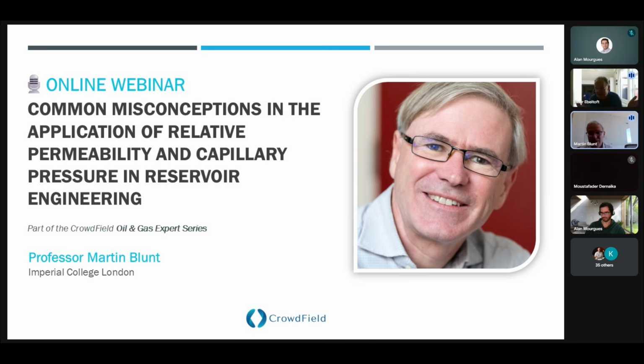Okay, what I would say there, Einar, is it could be lab artifacts, boundary conditions and things like that, but it is sort of the traditional drainage saturation profile. Well, I know what I would recommend. If you look at the equation, you see basically water being most non-wetting in a strongly oil wet system. So water is definitely non-wetting in the presence of oil. So if you're doing an experiment with mobile water and you know that it's oil wet, don't be surprised if you see gas wet type behavior. So what I would recommend is you don't dismiss those results. Capillary end effect is another subject for another webinar. But don't be taken by surprise and just dismiss it, because I think that is a genuine phenomenon.